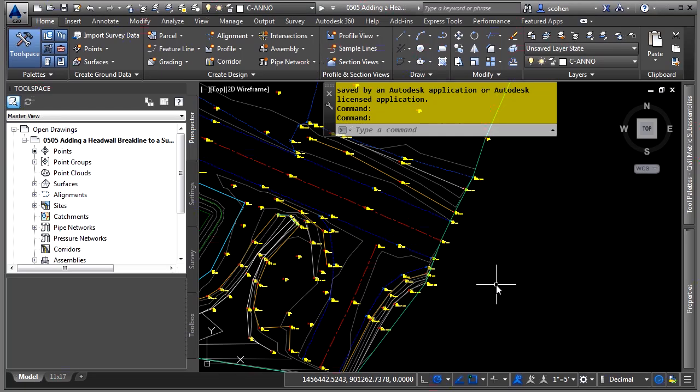Headwall break lines are very useful when you only have either the top or bottom northern eastern elevation of a feature, and either a consistent elevational difference between the points or you've actually measured the distance at each vertex when you were in the field locating the objects. This depth would, in most cases, come from the surveyor's notes, of course.